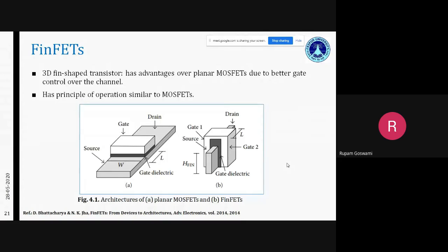You are able to significantly reduce the leakage current in these devices, and by modulating the dielectric thickness, you now have the opportunity of modulating the gate on three sides. So for example, with a gate with a different work function on one side and another different work function on the other side, to just modulate the carriers in your fin-shaped field effect transistors. So in a very layman sense, it gives you the degrees of freedom to explore so that you have more control over your fin-shaped channel.